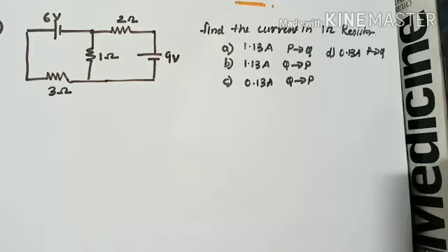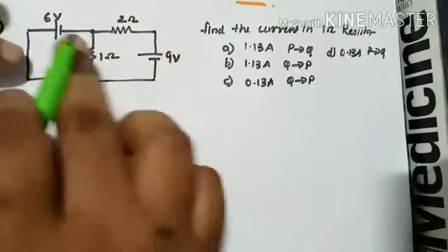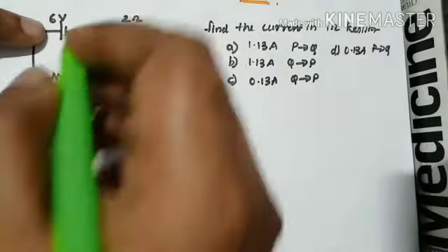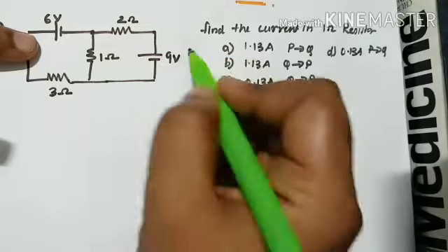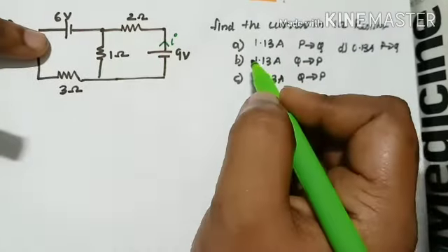Okay, now I'm going to solve the question as I have taught you guys earlier. Whenever you are doing KVL, what is the first step? First is to mark the current. There are two supplies, right? So we'll take one of the supplies, the major one. Since 9 volt is greater than 6 volt, I will take 9 volt, and current I is flowing from the 9 volt supply.